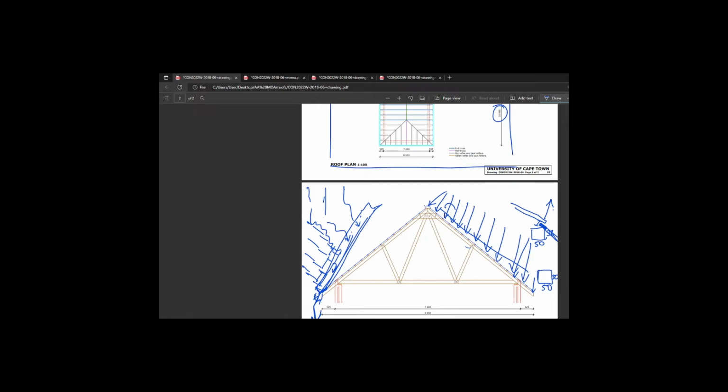Pretty clear. So let's say the tile is 25 mils thick. Maybe that's a bit too thick. Anyway, that's fine. 25 mils thick until it gets to this poor little end bit, and it's not propped up by anything, guys. So in order to account for this tile's thickness, all along here is resting on a tile. All of it, except this one. We need to either increase the size of our patterns. In this case, we have a 50 by 38 turning into a 50 by 50.